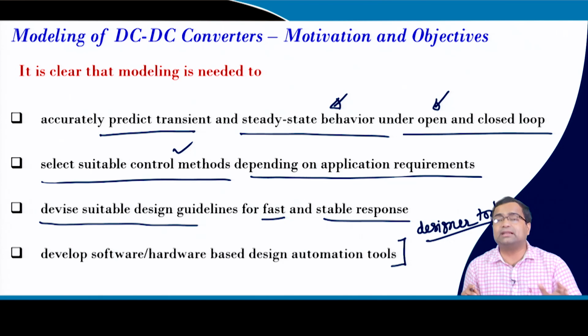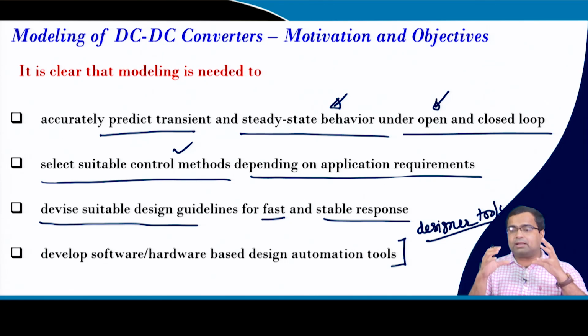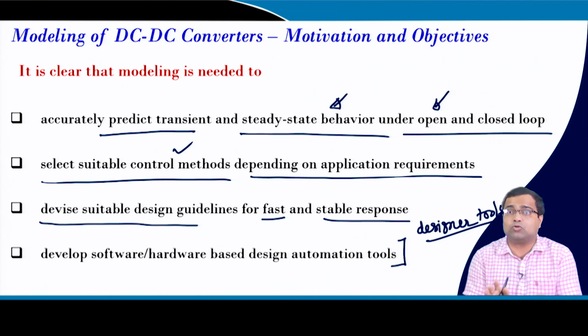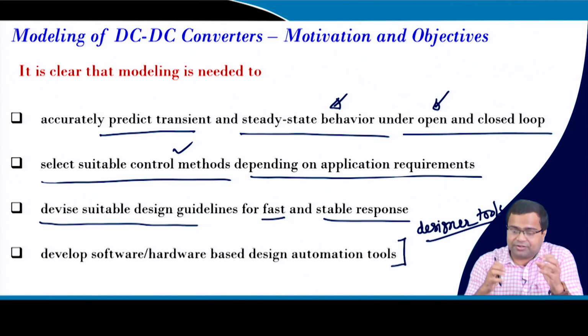The objective of this designer tool is an automated tool where you need to plug in a lot of models, and that will ask for your input voltage, output voltage specification, and load current. Then using that information, it will first select what my inductor value, capacitor value, and switching frequency will be. Then it will try to correlate across different industries what their existing products are close to that, and what range of products can meet certain input output voltage specification and load specification. Then it will give you different variants.